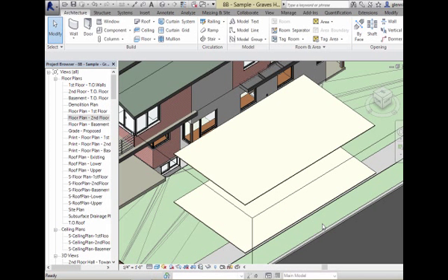floors. So stairs, again, the big thing about the stairs you have to think about is there's a floor-to-floor height difference, and we have to break it up into a set number of risers. Now the rules for the risers, by default, Revit will assume a 7-inch maximum riser, which actually isn't as tall as they can be. Residentially here in the US, we could actually make them 8 inches. So that's a type property, and we can go ahead and change that. Maybe I'll show you how we can change that.